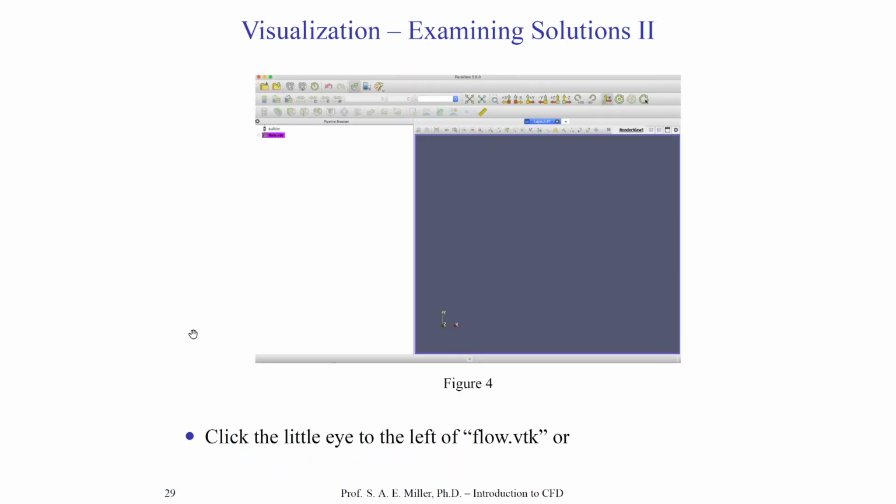If you make a mistake and can't see the model anymore, you can use these buttons up top here to reset the views. Just click them and it'll reset the particular views. You can click these scaling buttons here to scale around the model and change the axis views. You can also rotate the view here. You can change, of course, the display, the axis down here, and you can rotate around by clicking and dragging with these buttons up here where my mouse is moving. So get used to those. Those are just for visualization in the gray box. Remember, you're always clicking and dragging and mouse wheeling for moving the model around in the gray area.